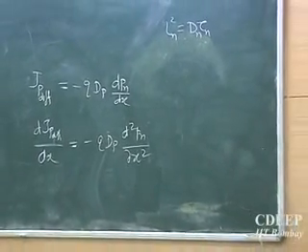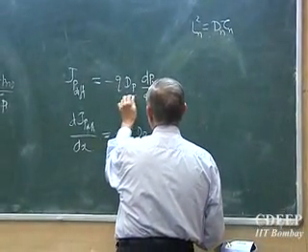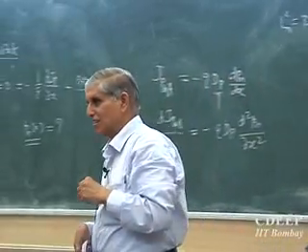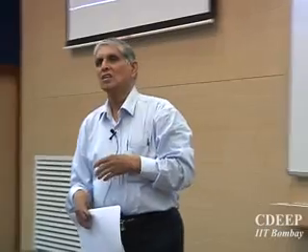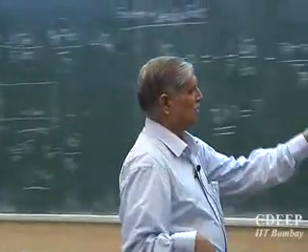Just differentiate. Now, normally, in all our assumptions, we say Dp is constant. But in reality, Dp may not be as constant as we thought, because Dp is related to mobility. But mobility itself varies with concentration. So obviously Dp is also varying with concentration. But in first order of simple thinking, we assume both mu and D constant for these evaluations. In reality, if you write programs in some kind of software, D also will be a function of x. However, right now assume that the diffusion coefficient is constant. Therefore the differential does not take care of that. We just write this term.